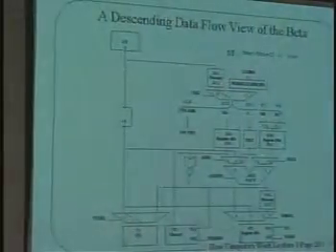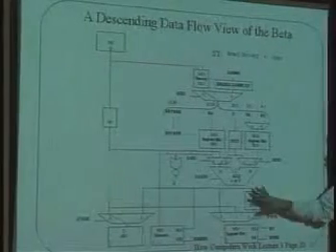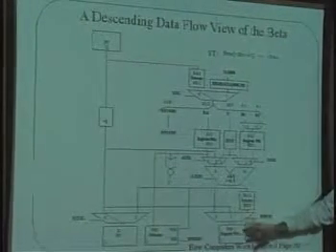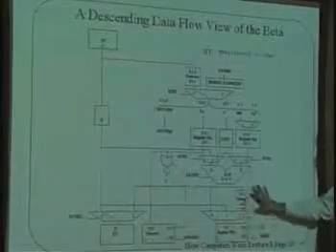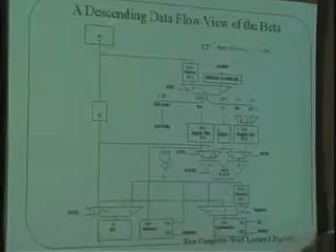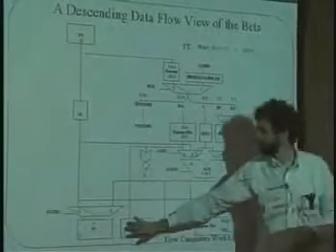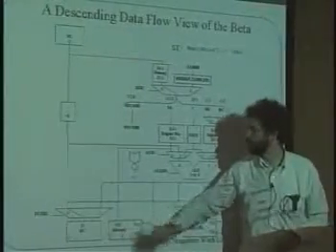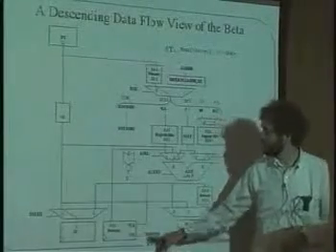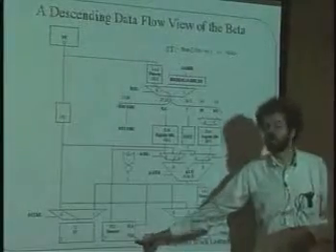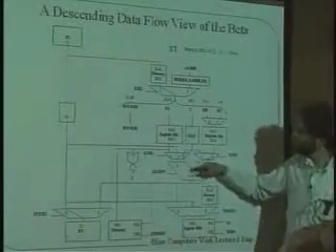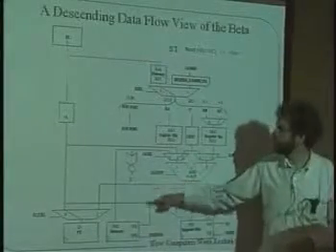Okay, load to store. Let's go back and forth. Here's a store. In a store, we're not going to be using the read stuff at all, and we're not going to write to the register file at all, so you'll notice this is all dark. However, what we are going to do is we will use the write path of the slow memory, the big slow memory, and that's over here. And this is now being turned on for the first time. So WEMEM is now on, and the data that pops out of the ALU is going to go to the memory system.